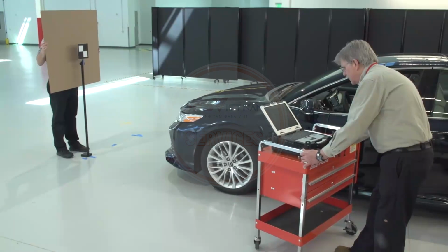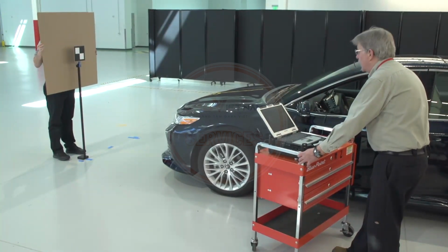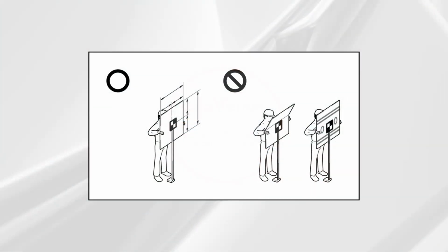millimeters. In case there are problems with target recognition, place a large piece of flat cardboard with no markings behind the target. As shown in the repair manual, a wrinkle-free light-colored plain cloth could also be used to block background objects that might cause target recognition issues.